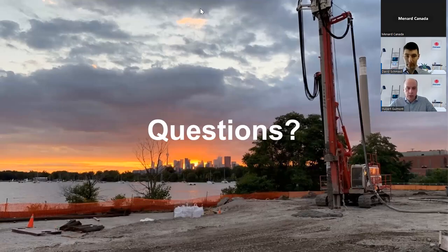Any other questions? So we use Plaxis in our modeling most of the time. We also have some in-house spreadsheets that we've developed through the years. A lot of ground improvement is semi-empirical, so we also rely on our experience and on the large number of projects that we've performed through the years. That, of course, helps us when it comes to designing a project. So it's not only modeling, really. It's hard to model. For example, dynamic compaction is very difficult to model.